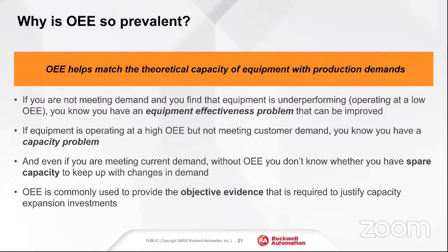But here is the thing: because the target is based on schedule or present demand and not on theoretical capacity, you might be running at a greatly reduced speed, or at a reduced level of performance, and still reaching your target, right? So now when a focus team applies the OEE to each step in the production line, or a plant, or each machine, they can usually readily identify opportunities to reduce those 6 big losses that we discussed.